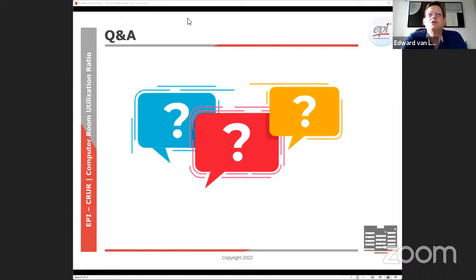The other portion is, of course, the actual usage as it is today. That can be obtained by measurement through what is already available on the systems. It could be read on the display; on the UPS, there is a display showing the power ratings. But more and more, people have implemented a BMS or DCIM, and then you can pull that data from those systems if you know which parameters to look at.